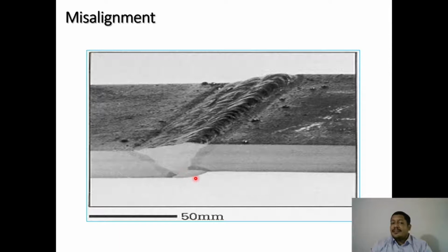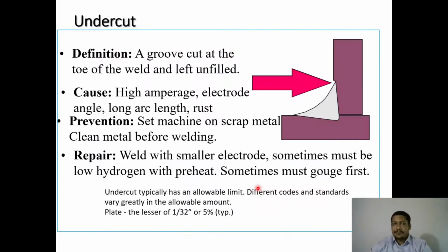Now, if I want to avoid it in this area properly, on this plate I have to machine, so on this side the material thickness is going to reduce. That is the remedy here, but it depends on the application. If you reduce the thickness on one side of the plate alone, slowly you can see defects, cracks, bending, or sometimes failure will take place on this side. So proper fit up you have to take care of in the case of welding.